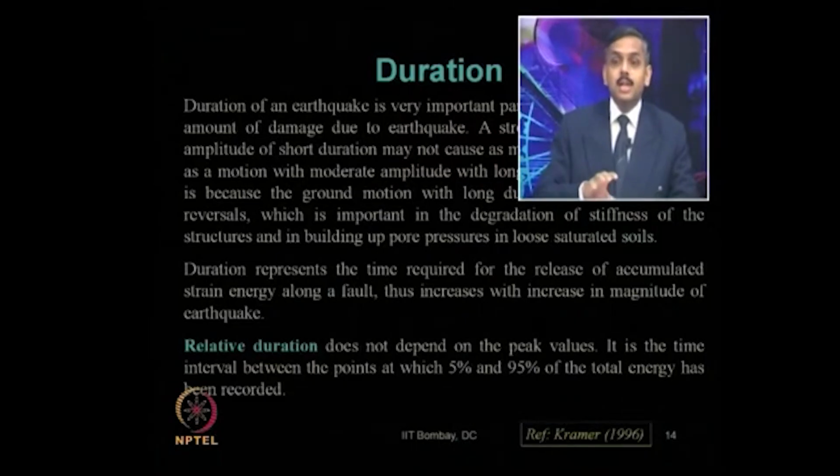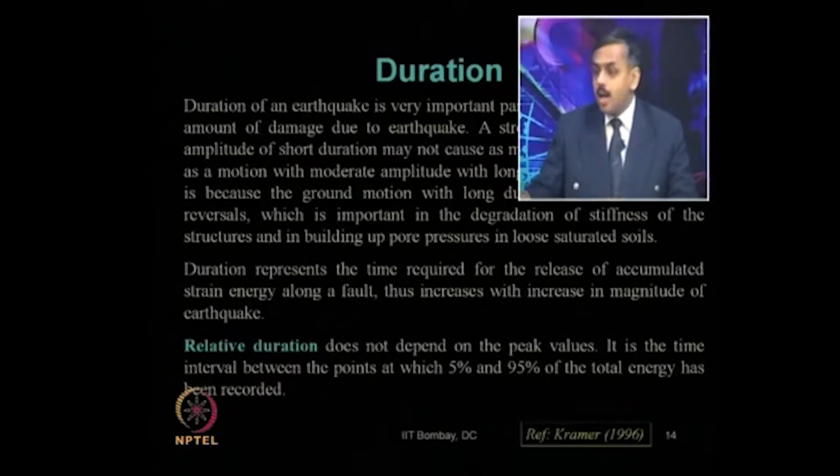Automatically that also creates a problem, say liquefaction or a loss of effective shear strength, which ultimately reduces the strength of your foundation soil, etc. And of course, the structure reduces its stiffness due to more load reversals. So, a longer duration earthquake is always more damaging than a shorter duration earthquake.